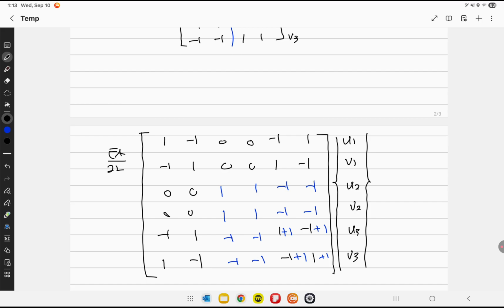So boundary condition. What are the boundary conditions? U1 and V1 are both 0, and U3 and V3 are both 0. Do you agree? So how did Dr. Dong say to apply the boundary condition? You said the reaction forces are unknown, and if it's attached to the wall in this case, then the displacement would be 0 as well. Yes, true, but it's too complicated.